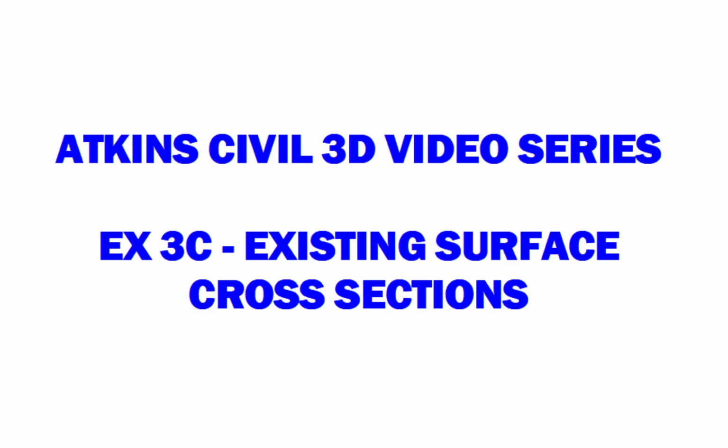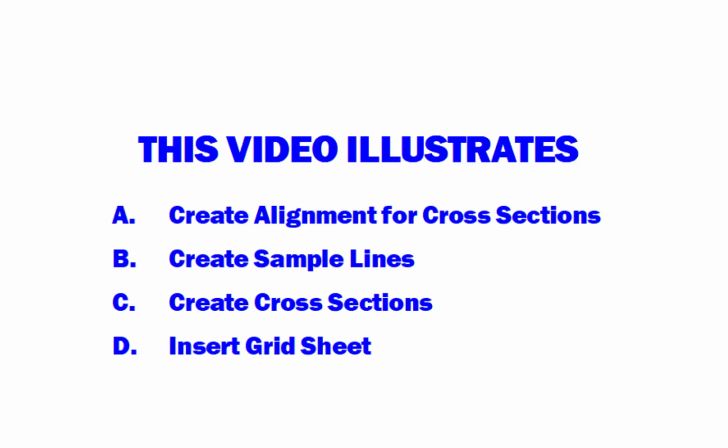Atkins Civil 3D video series, existing surface cross sections. This video illustrates: A. Create alignment for cross sections, B. Create sample lines, C. Create cross sections, and D. Insert grid sheet. Generally, cross-sections are prepared after the alignments, profiles, assemblies, and corridors have been created.